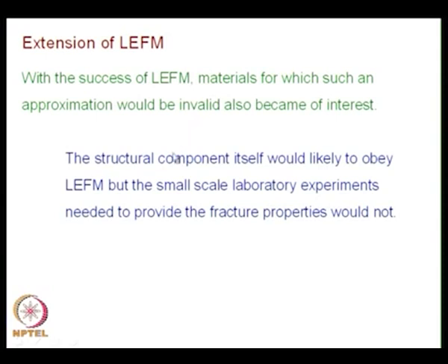And there is also another observation that has prompted people to go in that direction. The structural component itself would likely obey LEFM, but the small scale laboratory experiments needed to provide the fracture properties would not behave in such a fashion. So, this is another angle to it.